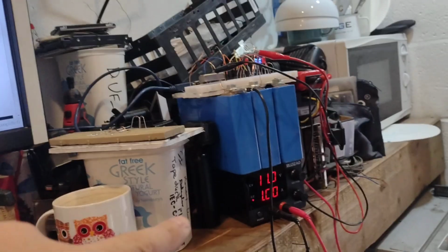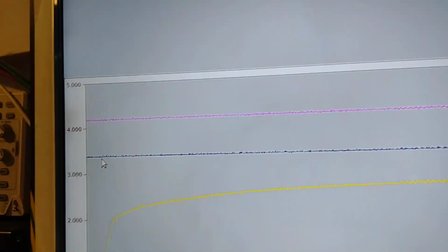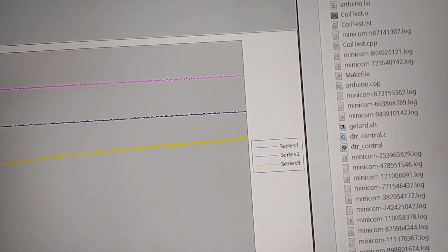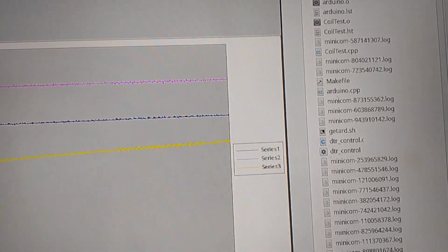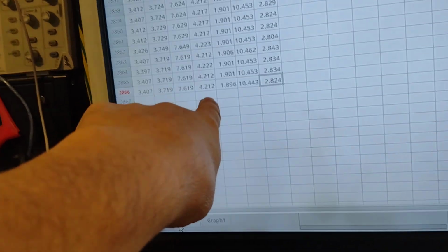So what's going to happen now is this will then charge it up to the 12 volts, right? But only one of the cells, this one, is actually going to be anywhere near fully charged. In fact, it'll probably be over the voltage I'm setting it at, which is 4 volts. And it's currently actually above that anyway, isn't it? Because look at it. I'm going to have to reduce it because it's currently at 4.2, which means it is actually fully charged. I don't think it is.